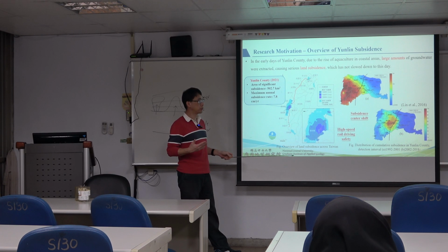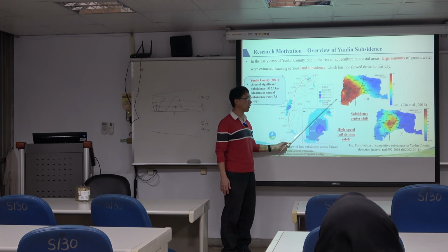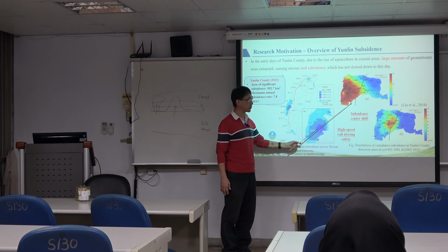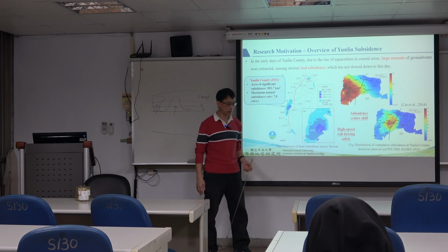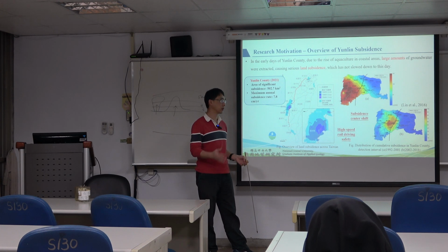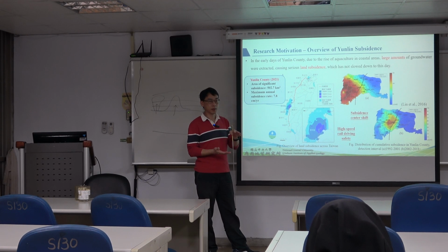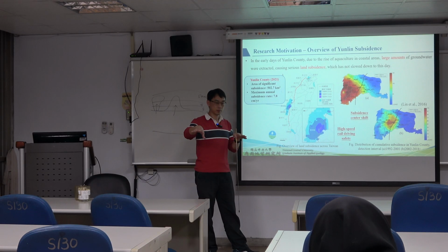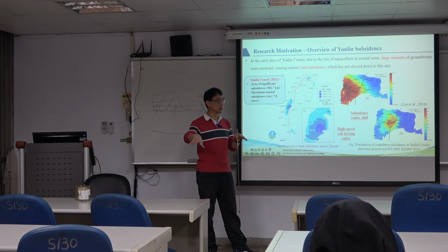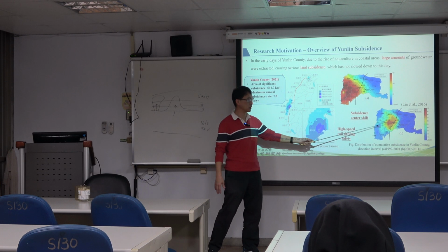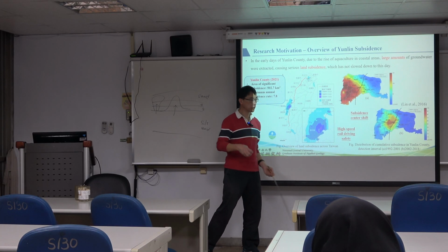Some of the professors proposed that this one is the historical subsidence because they pumped a lot of water in that area for the aquaculture activities. So after a period of time, the clay compressed and became like a permanent displacement. They reached the steady state condition, reached the final compression, so they do not compress anymore. And right now, the new pumping occurred inland, so we can see the continuous pumping here. So they proposed this concept.